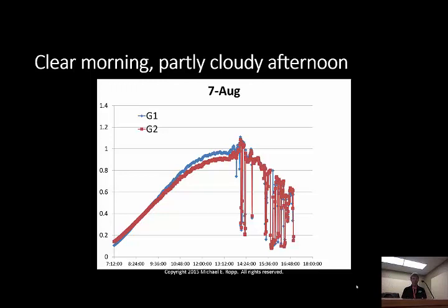And when that passes over the array, the irradiance can drop from close to about a kilowatt per square meter, which you can think of as 1 per unit, down to as low as about 0.2 per unit. And we've seen cases in the field where relatively large PV plants can do that 100% to 20% drop in 4 to 8 seconds. So it's a significant ramp rate.